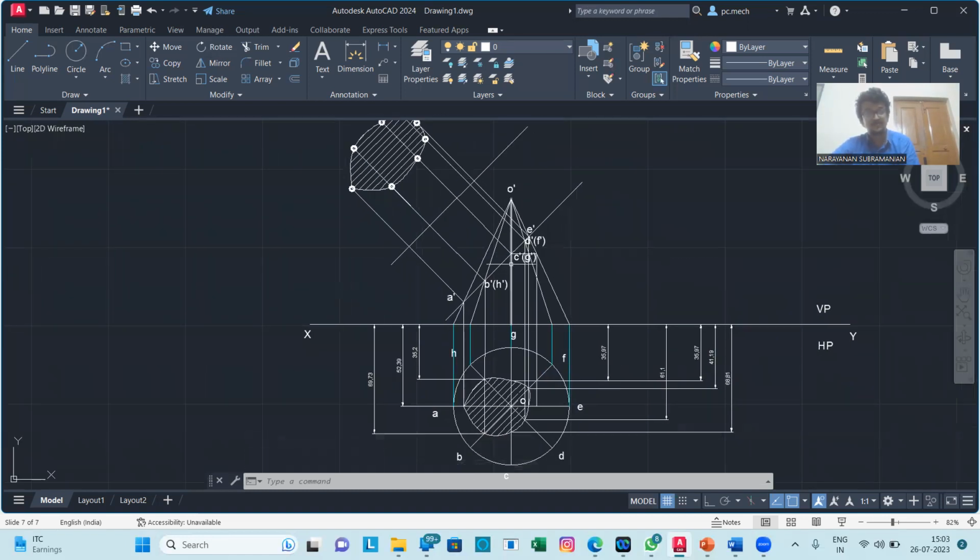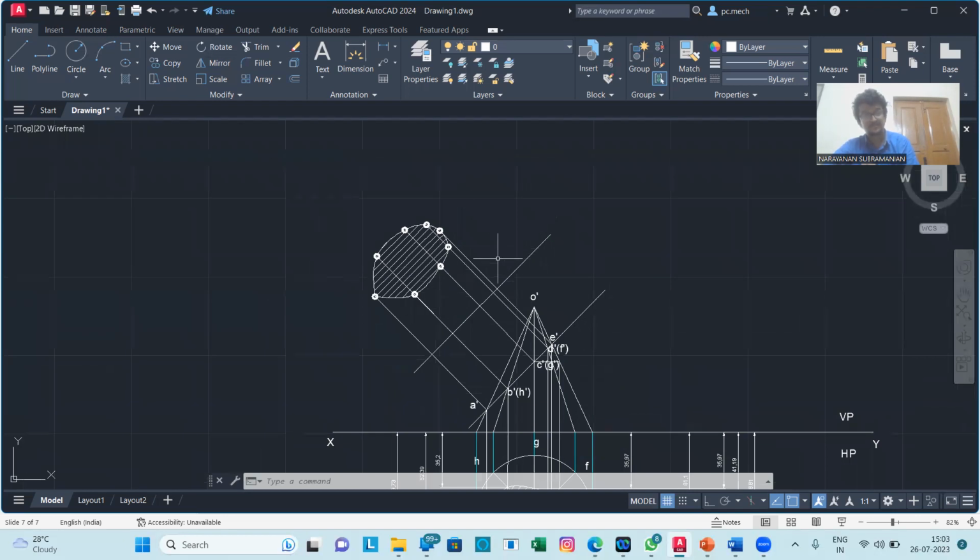So this is the front view of the prism and top view. This is the sectional top view. So when the prism is cut, how will the top view be? What will be the true shape of the section? How will the sectioned cone look? The true shape of the sectioned cone. You are sectioning it with an inclined plane. How will it show up here? So you just imagine the shape to be here in 3 dimensions, right? This is how the cone will look.